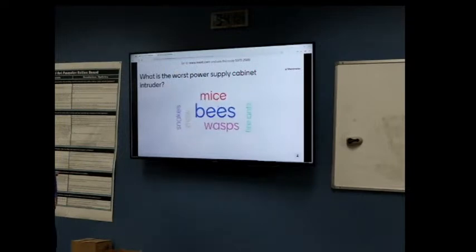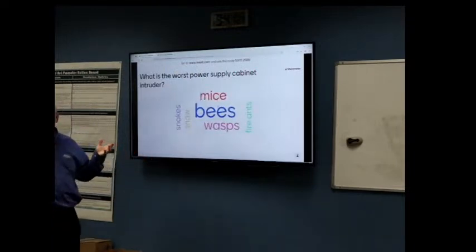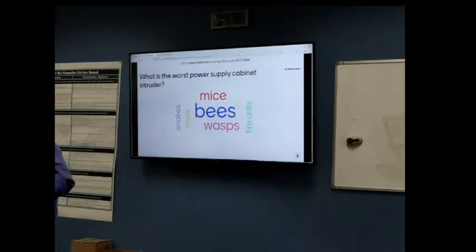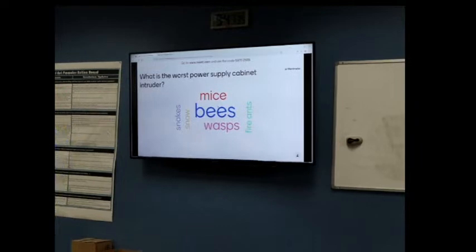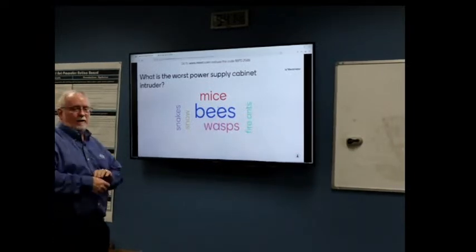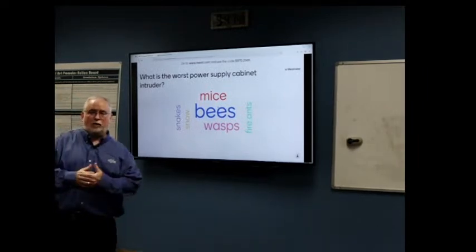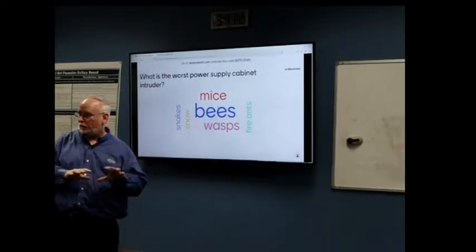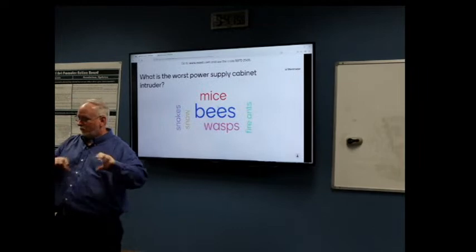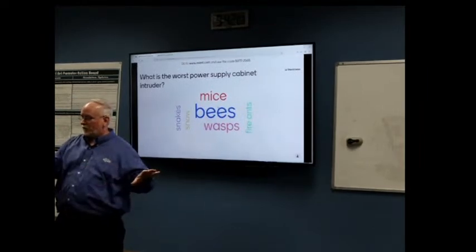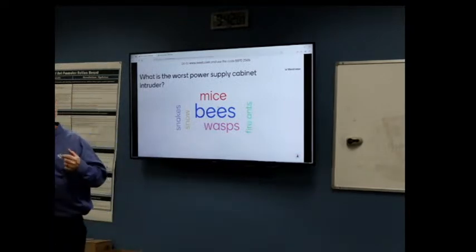So this stuff is real, right? This is what we have to deal with every day. There is a power supply routine maintenance document out there. It's called the SCTE 205-2014 Power Supply Maintenance Document. One of the things it goes through is looking for vermin and stuff like that. And I'll be honest, we try to mitigate that. If you guys are doing any ground mount cabinets like a PN4, one of the things that we suggest is to put 30-year felt down underneath. So you put down either your precast pad or your formed pad, and the first thing you do is put down that underlayment to try to keep little creatures from coming up.